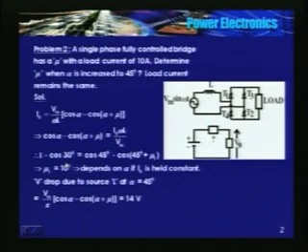So therefore, don't assume that just because Vm is held constant, the source inductance is the same, and even if I keep the load current constant, mu, the overlap angle, will remain constant. No, it depends on alpha. A very important point to be noted. When alpha is equal to 0, when it is triggered at 0, the commutation overlap angle is 30 degrees. Now when it is triggered at 45, it reduces to 10 degrees.